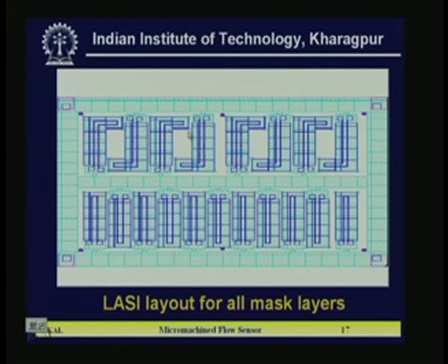So, you can etch from the top, and from the bottom you will etch only the region where your film is. That means in this particular case the nickel film is here, here and here, and in the structure 1 case the nickel film is only in this portion, this portion and this portion.